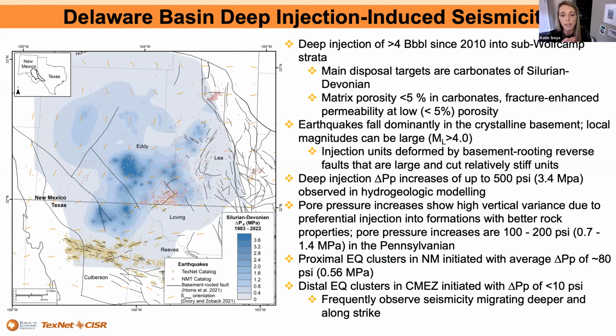So not specifically. I will say though that it is reflected in our pore pressure model, in that the pore pressure model is not a black box model. It's based on the geology. And so if there is an effect of thickness, for example, allowing more storage capacity, more pressure diffusion, more connected permeability pathways, that will be reflected in our pore pressure model. It's a great question. Good line of research.